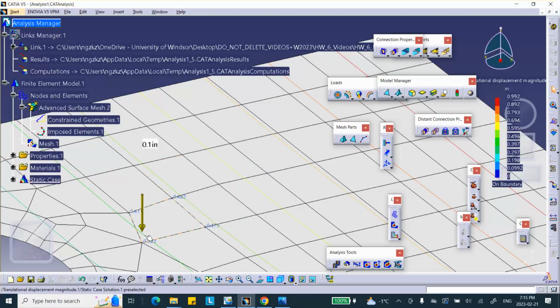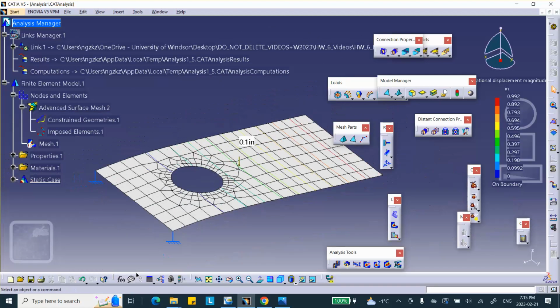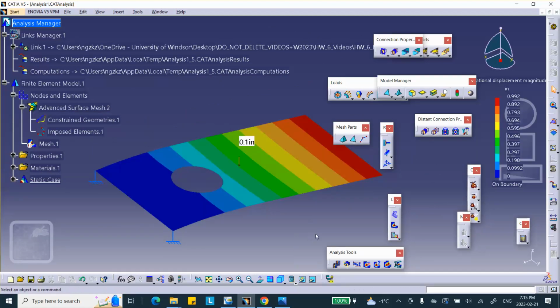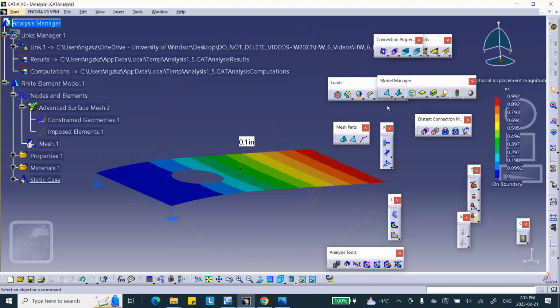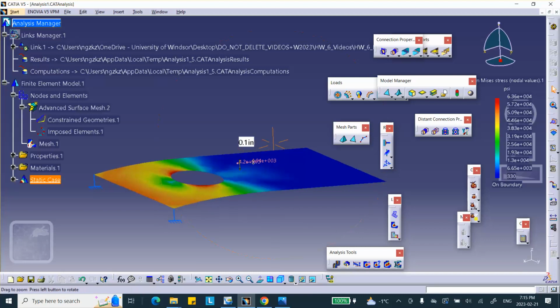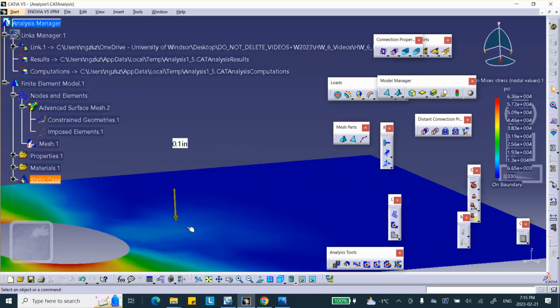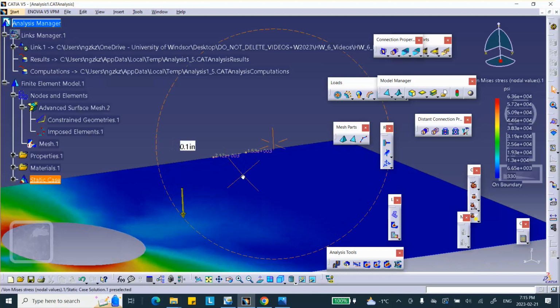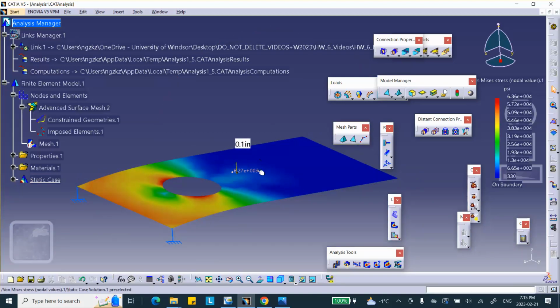And right there, this is where I applied the force. Remember that? And you can change the rendering to material shading. You can see the colors. And if you look at the Von Mises stress, because I put a force right there, you can see this color is a little bit less bluish. So there is kind of a stress concentration over there. Of course, the big stresses at the stress concentration around the hole actually mask this right underneath the load. And that's pretty much it.